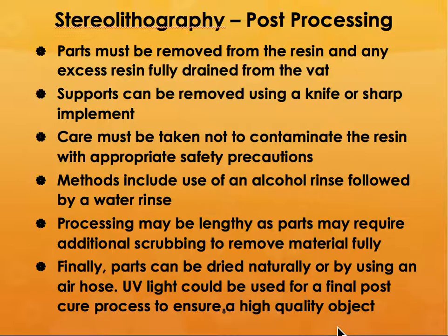The parts must be removed from the resin, and the excess resin is fully drained from the vat. If there are supports, then you can remove them using a knife or sharp device.